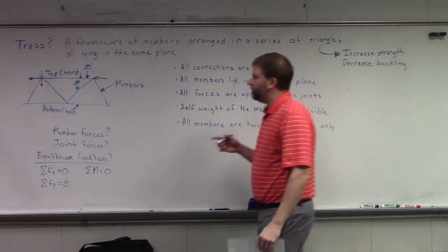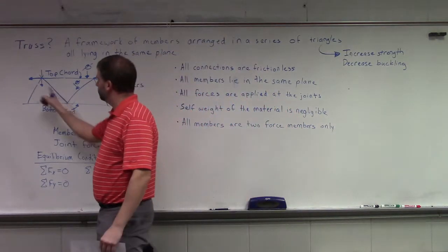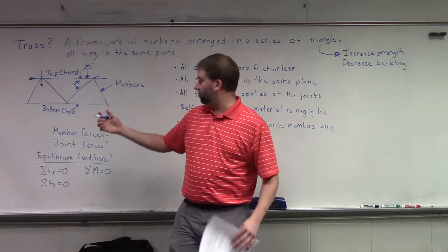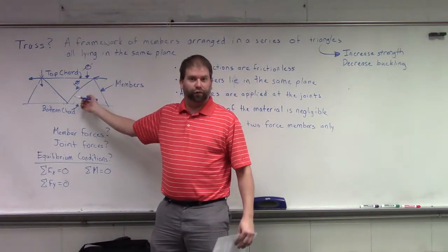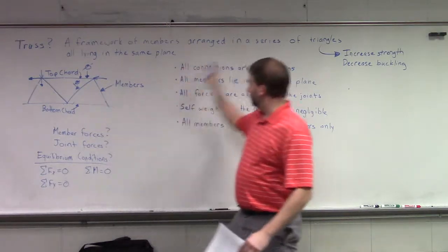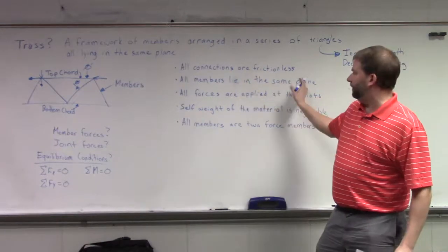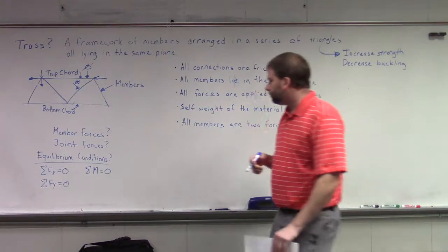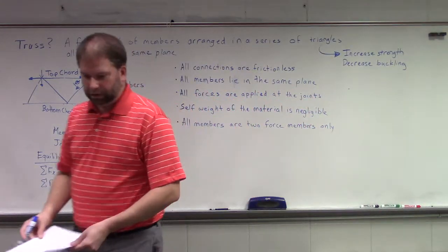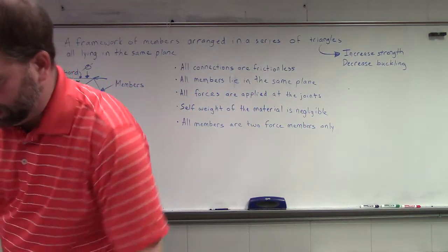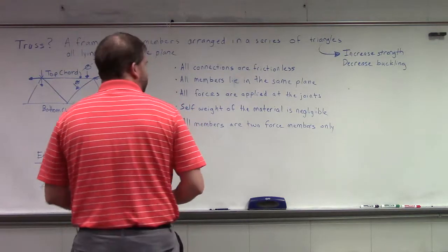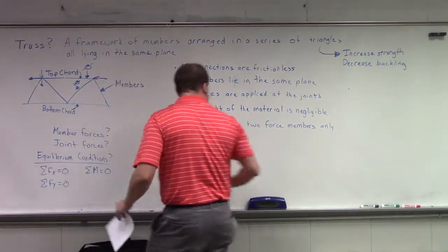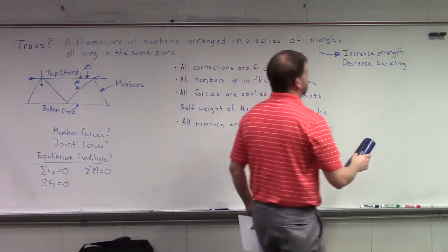So the joints are much easier to calculate, but in actually sizing out a bridge, we're more interested in our members. Because if we know the forces on our members, then we can blow away all those assumptions and actually size this thing out. Okay? So that's what we'll look at. We're not going to get into too great of detail in the method of joints. In fact, we're not even going to go this far because I want us to get into the material. So